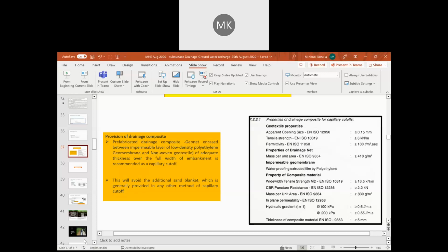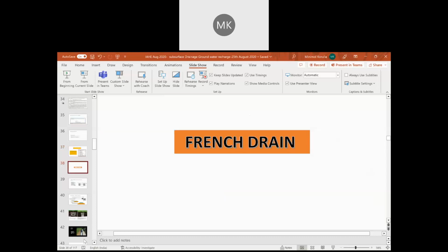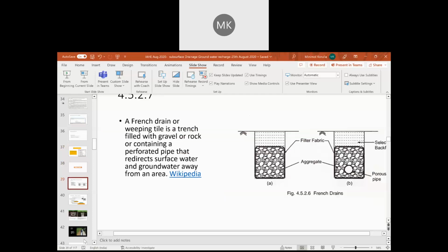So if we are summarizing the points I told, the problems with the conventional drainage media are unavailability of cheap granular filter media, poor gradation of gravel media, choking of media. Yeah, gravel drains can get choked. Whereas the advantages of geosynthetic drains are, definitely there is a big cost effectiveness. You can achieve directly 30 to 40 percent cost advantage. Then customized performance to suit the application. It is a tailor-made material.